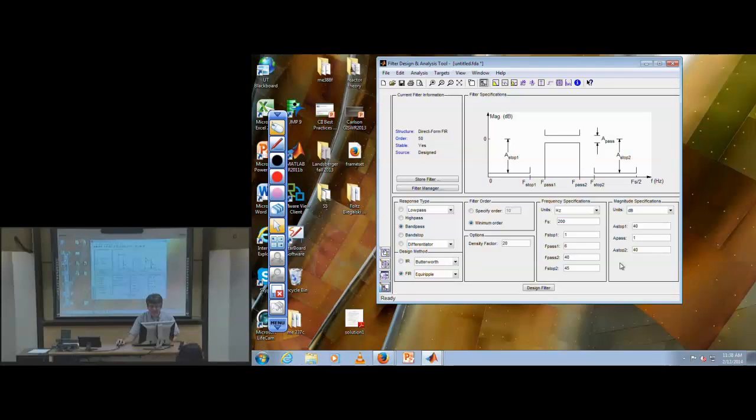Why did you choose the stop frequencies to be 1 and 45? I chose it, and I gave some explanations; this was an ECG filter. So there are some frequencies close to 0 you want to eliminate. So that explains it, I want to stop frequencies from 0 to 1, low frequencies. I have a power line frequency that's going to interfere at either 50 hertz or 60, depending on what country I'm in. So I put that in the stop band.